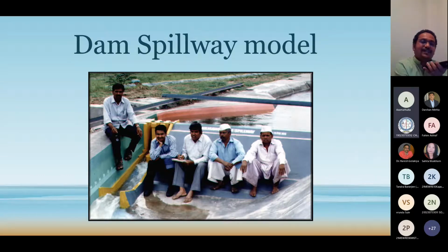Okay, you can also see near here. Here you can see roster tail forming, I mean, in front of the pier. Then here also the same problem, meaning high velocity jets at the right bank. So previously, for the Parbati dam spillway, then my boss, Kashyap Sahib, we suggested the dam axis should be changed. Then only can we save the right bank. Otherwise there is a safety concern. Here you can see. Next slide, please.